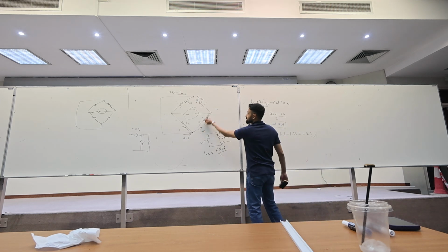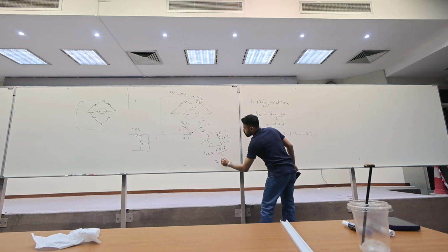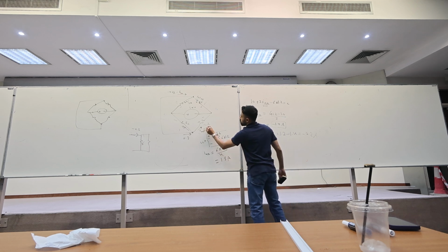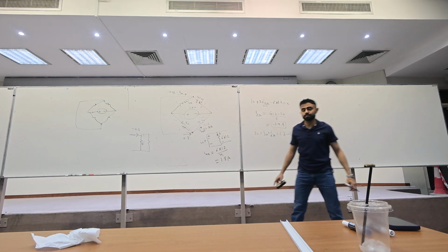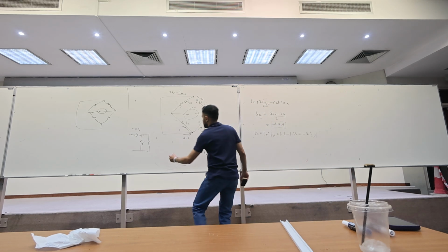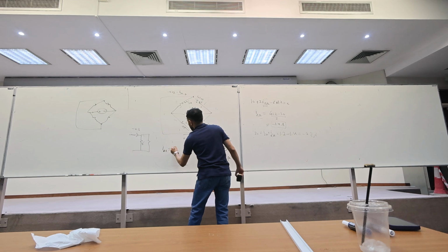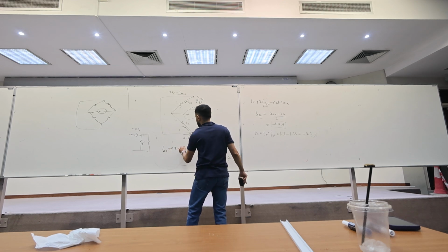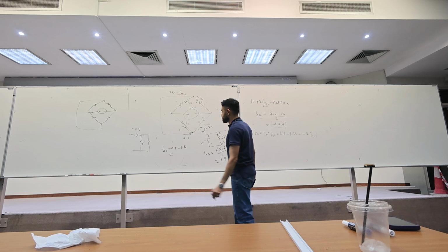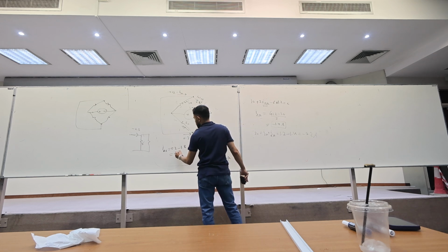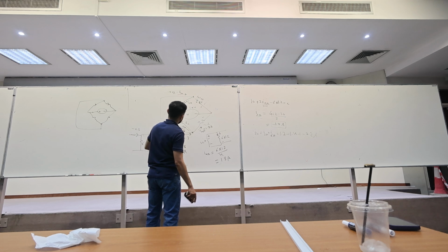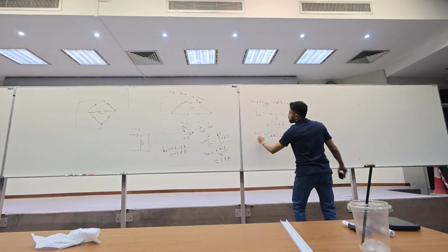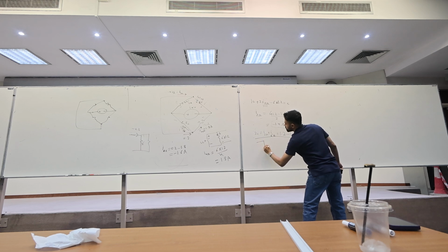So now I calculated this current. What's the answer? 1.8 amps. So here I know I have 1.8 amps. Given that these two resistors are in parallel, they have the same voltage. So what is IRx? IRx equals 0.2 minus 1.8, which is equal to minus 1.6. So here I have minus 1.6 amp. We repeat the same trick. We have the 2 ohm in parallel with the Rx.